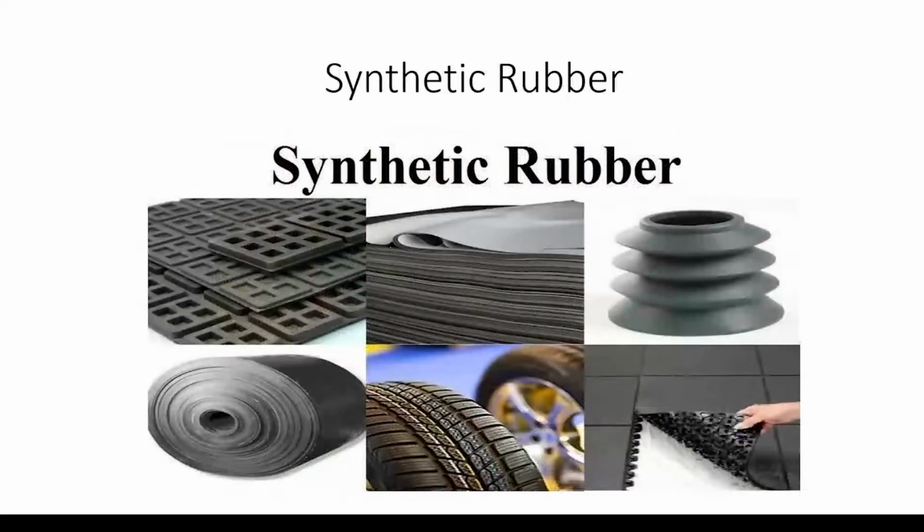So next one is synthetic rubber. Synthetic rubber comes from oils in various forms, so it is also dependent upon reserves of oil. Then it is tailored to provide particular properties such as oil resistance, flexibility at extremes of temperature, and resistance to ozone. It also cannot be regarded as capable of replacement by natural rubbers, although synthetics can be used in place of natural.